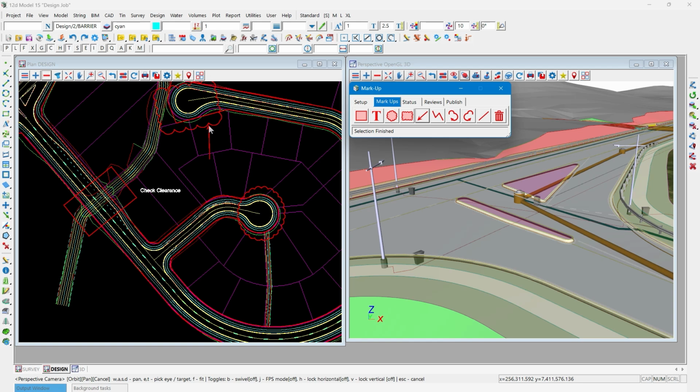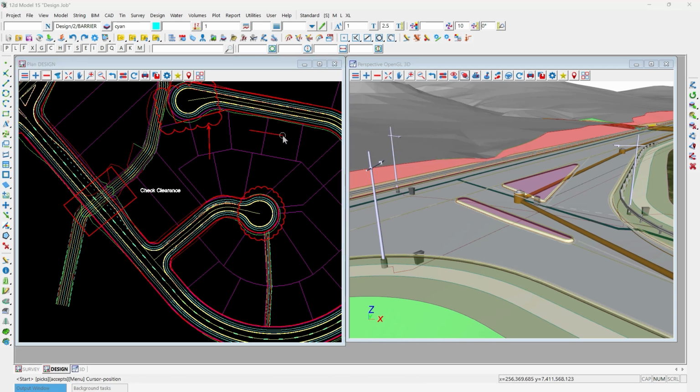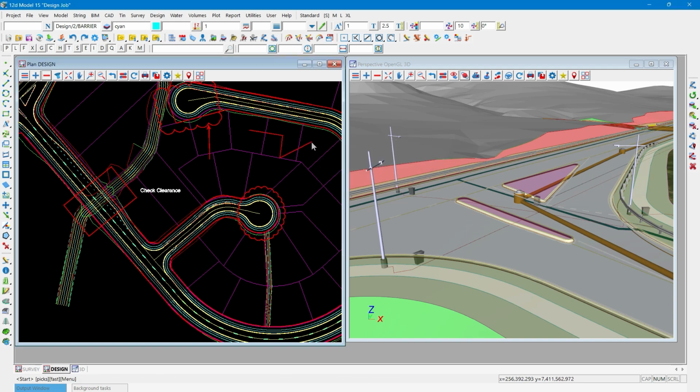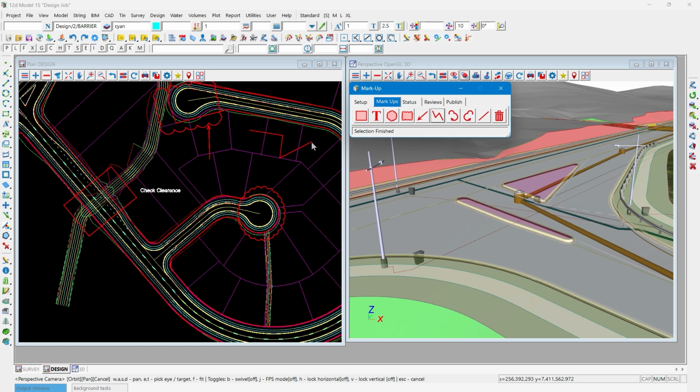You've got the ability to have a line string, which is a string with more than 2 points. So you can highlight something else, draw something the way that should be. And with all of these options within the markup, you pretty much want to keep an eye on where you are in the status, because the commands are cancelled, or to get back to the markup panel, it's escape on the keyboard itself. So if you're ever stuck and you're not too sure where the markup window went, just hit escape and it should pop back up again.